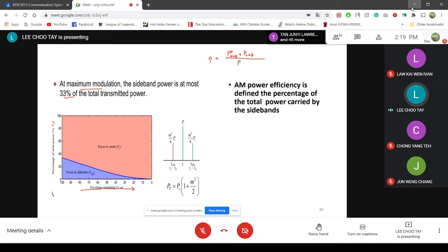Because in practice the filter window depends on your n, on your order of filter. If you use an n which is low, you won't be able to get this lower sideband out perfectly, because you're going to get something like this again. That's for a filter of a very low order.